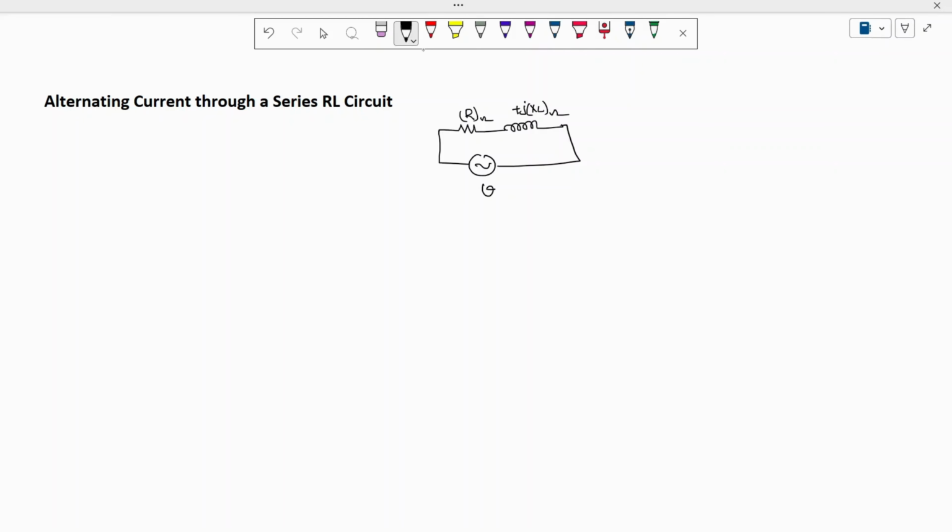Okay, so now whenever the current enters, I'm labeling this current as i(t). Entering is positive, leaving is negative. The voltage developed across the resistor is VR. The voltage developed across the inductor is VL. Okay. Now, when you apply the KVL, actually it is an AC supply, so we should not mark terminals. Why I marked the terminals is to make the analysis easier.